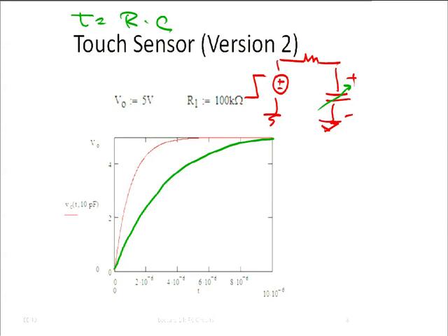And so at some time t equals 0, we turn on our source, okay? Then at time t1 is when we reach 3 volts without the finger present. Now at some other time that is longer, t2, we also reach 3 volts when the finger is present. So if we somehow had a contraption that could measure these times, t1 and t2, we afterwards easily could determine whether no finger or a finger is present by simply comparing these two numbers, right?